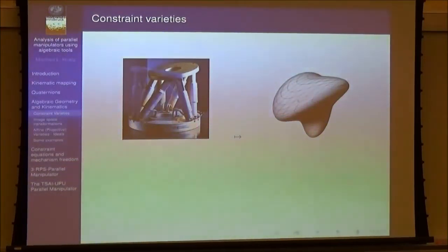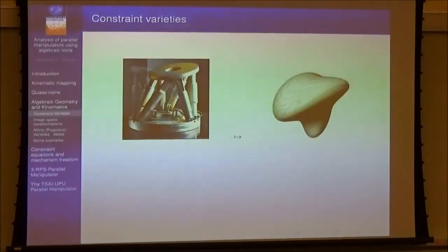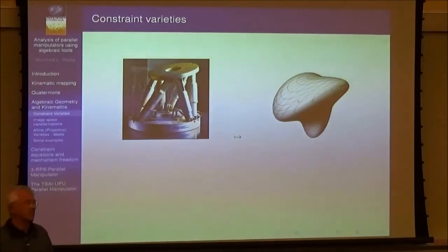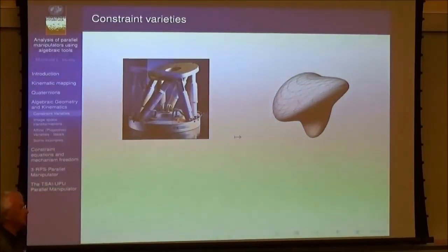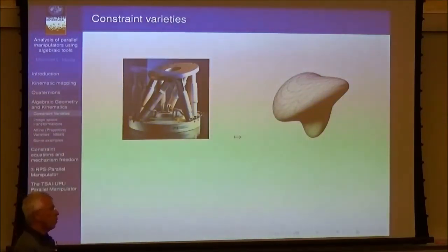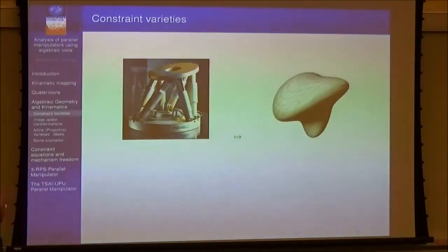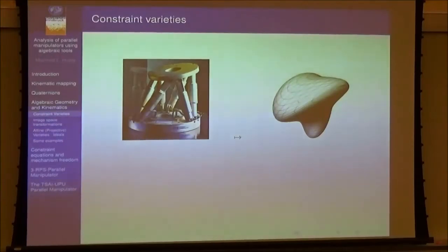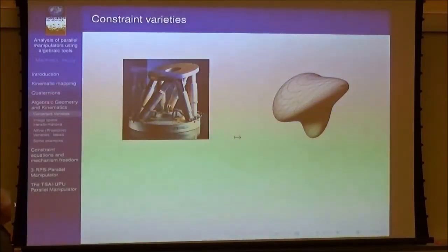It could be the inverse kinematics, or the question, where are the singularities of this manipulator, how can we analyze this manipulator. So what we can do is try to find out what are the so-called constraint equations describing this manipulator. What is the mathematical description of this manipulator?